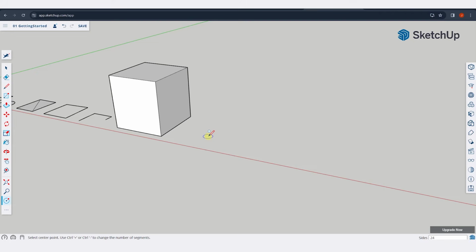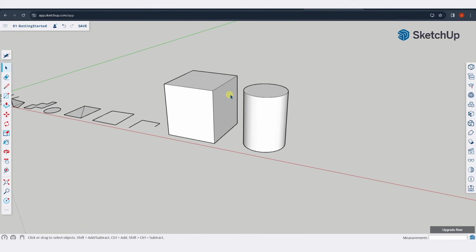And you can do this with any flat shape. So not necessarily curved surfaces, which we'll talk about in a second, but if I tap the C key, single click, and move my mouse and then click again, I can draw a circle. Well, if I tap the P key, mouse over a surface, and move my mouse, notice this is going to extrude this to 3 dimensions right here. And again, this is another place where single clicking is really valuable, because now that I've single clicked in order to activate this tool, I can mouse over whatever I want in order to set the height of the object like this. But you're going to use the push-pull tool a lot to extrude things to 3D.